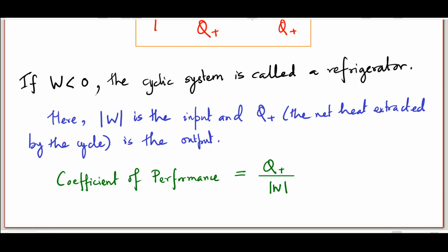Now, one thing which many thermodynamics textbooks talk about is what is the relationship between the coefficient of performance of a heat engine and its efficiency. Frankly, such a thing cannot make sense at all. A heat engine has efficiency because it's converting net amount of heat into work. The coefficient of performance is essentially a property of a refrigerator, something for which amount of work done is negative.